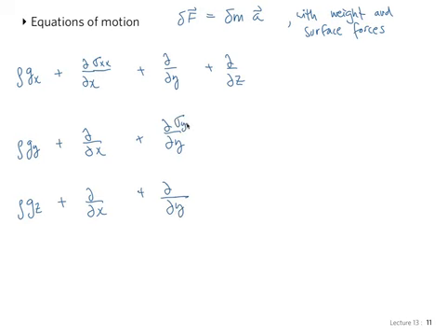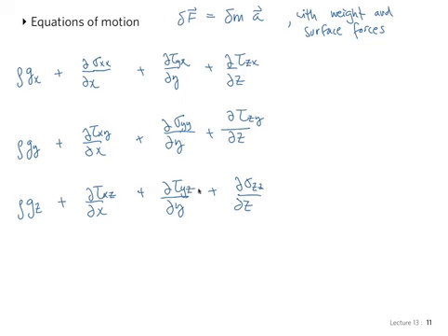This is the normal, and this is the normal, and we have... now the tangential ones were tau here, this point always in the x direction, right? This one was tau yx and tau zx, and this one was the point in the y direction, so tau xy, tau zy, tau xz, tau yz. Those are all of the terms there.